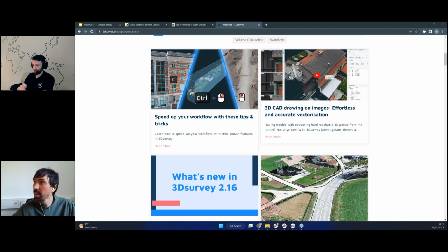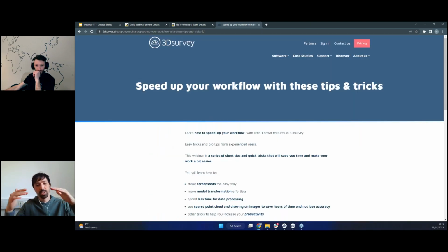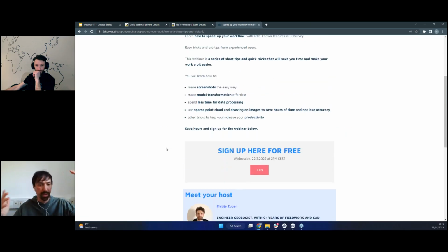To calculate a contour line map showing where the differences are bigger or not, let's think about how to do this one. I think CloudCompare has that kind of function if you would like to compare it. Otherwise, use color options, because sometimes the realistic colors don't help you so much. Right mouse click on the first surface, set the green color. Right mouse click on the second surface, set the red color, and then you have red and green to do the comparison. You will immediately see where the differences are.